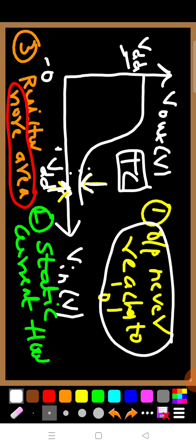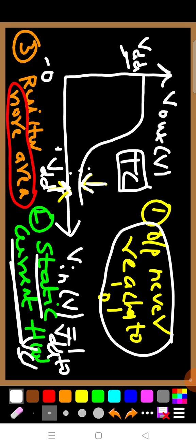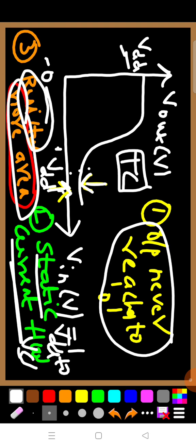When Vin is equal to 1, there is a path from VDD to VSS, which leads to what? Static current flow. And one more very important drawback is that even small values of resistor will occupy more area in the fabrication process.